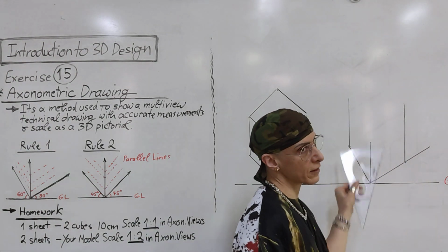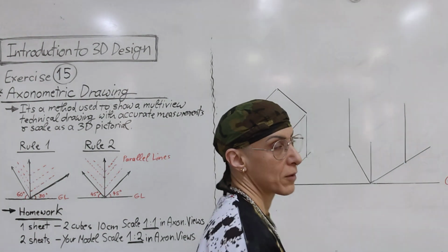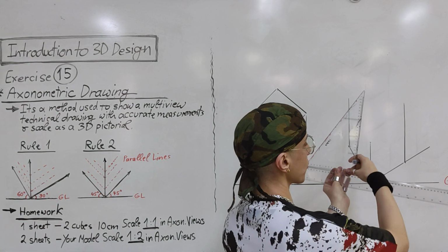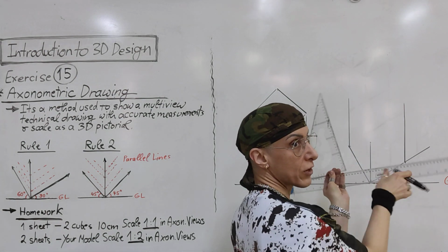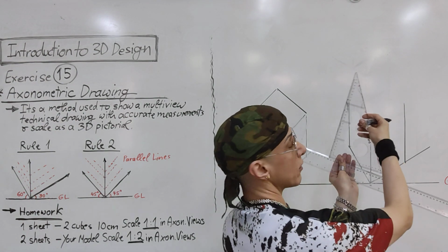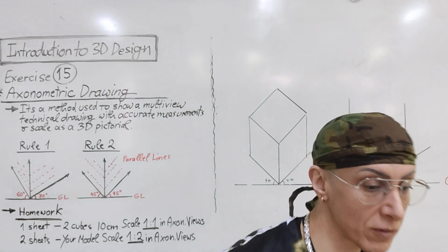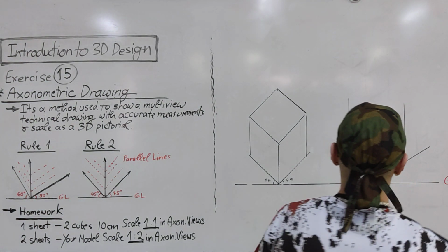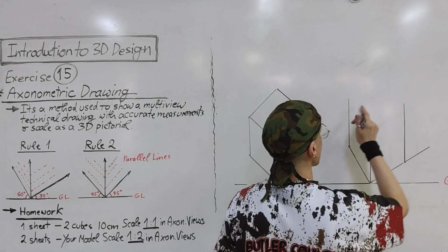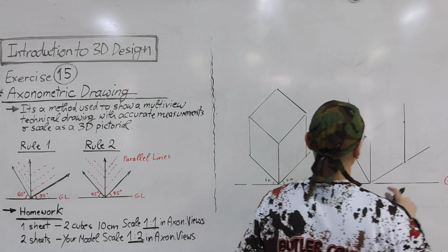Now, how do you draw straight vertical lines with the T-square? Just to remind you, if I put the ruler like this, I can draw straight lines. I can shift it this way, that way, or of course like this, the same thing, okay? But the T-square must always be present in these drawings. Now, here also we will measure 10 centimeter, and again here 10 centimeter.